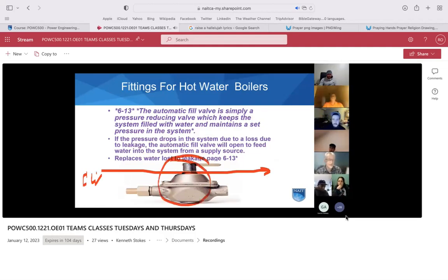So if we had a problem in this device and maybe the city water main broke out in the front street, like it did at my house 2 days ago, and I had a hot water heating boiler in my basement. Some homes have them, many homes have them. Buildings around the neighborhood, I was looking after boilers in a medium-sized building a few blocks away from here for a number of years. The water main breaks and the pressure in the boiler is higher than the pressure in the water main. This boiler water could go back into the water main.